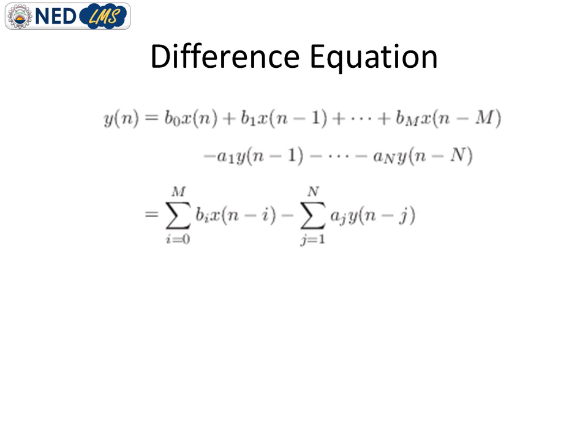And you can see that we have several coefficients associated with several time delays of the input signals, and several coefficients along with their delays associated with the output signal. So all these coefficients and their delays can be represented in a generic form with the help of this summation sign. b of i represents the coefficient associated with the input, and i represents the number of delays, how much delay this input is getting.